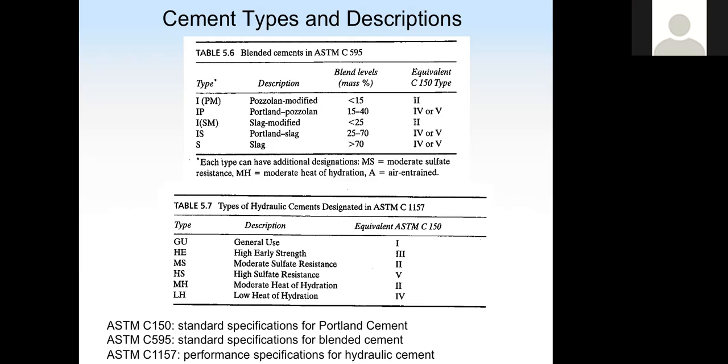Do we have soils like that here in Hawaii? I'm not so sure. I do not think sulfate attack is a major concern in our environment. But when you have an underground structure, it's always safe to measure the sulfate content, because you may have groundwater which may carry some sulfate.